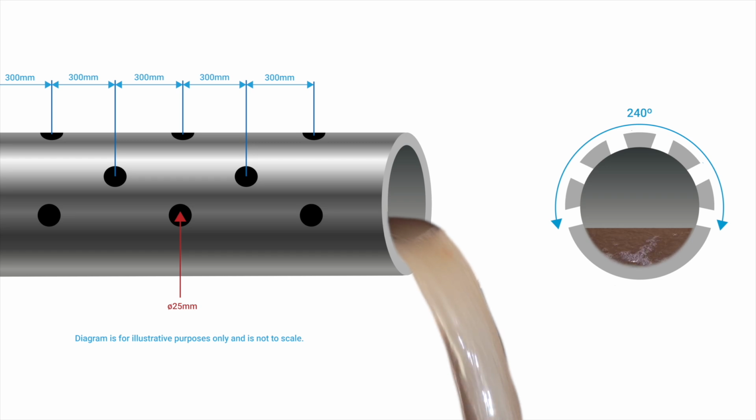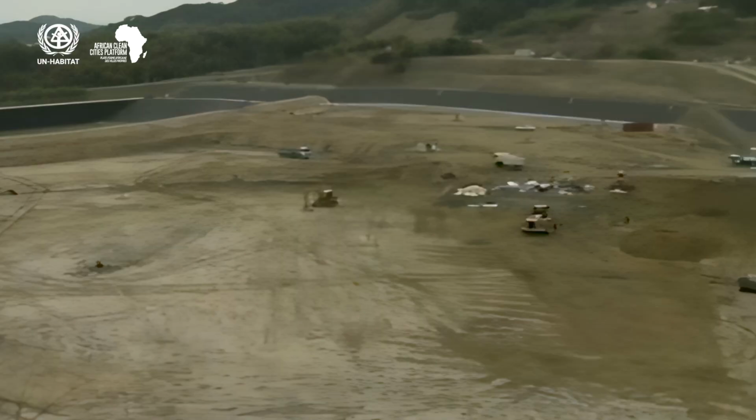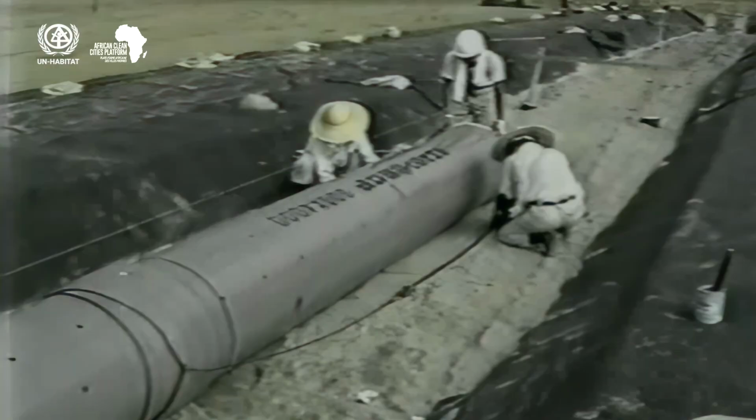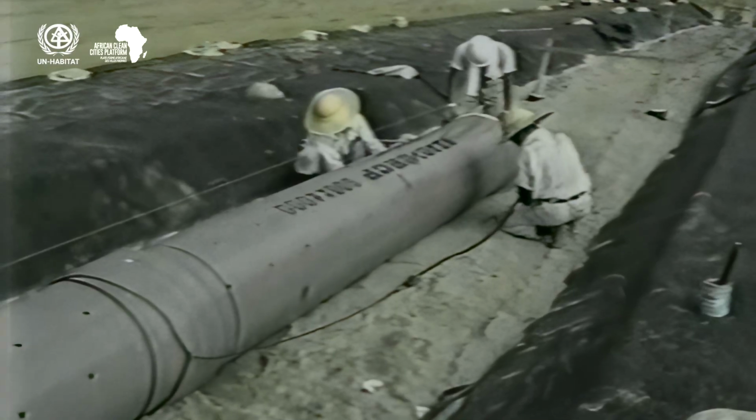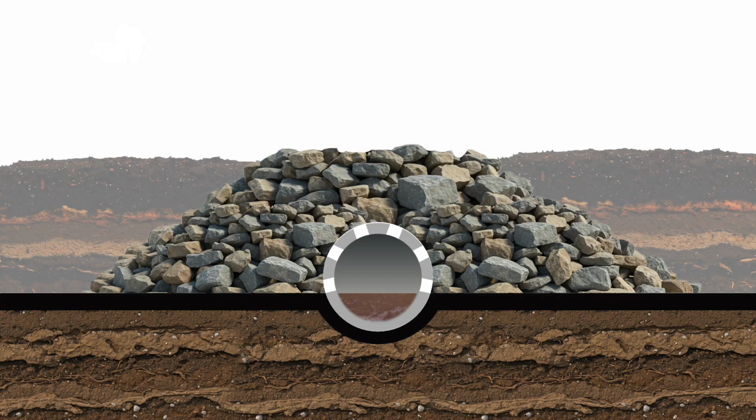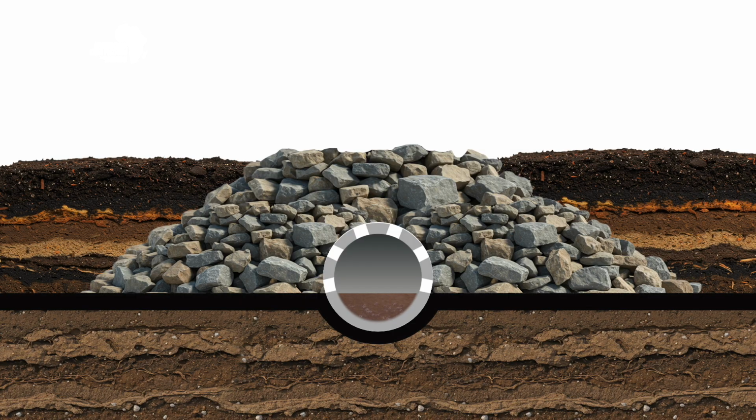An advantage of semi-aerobic landfills is that the risk and level of toxic leachate reaching and seeping into the ground is far less. So, whilst the geomembrane liner is always good, tightly compacted clay does an equally good and less costly job. The pipe can rest directly on the ground, either the liner or clay.